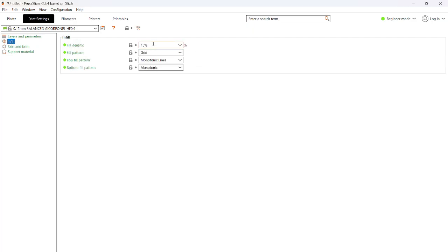For infill, you can change the density, but you can also change the pattern at which it does that. I'm going to leave it as grid. Again, if you change anything, it might add time and stuff like that, so you might not get a consistent result. So minimizing these changes, or at least copying what I changed for this assignment, is what you should be doing. But these are all available to you.